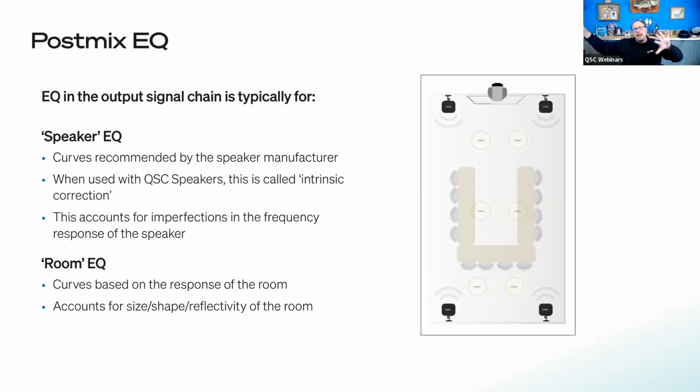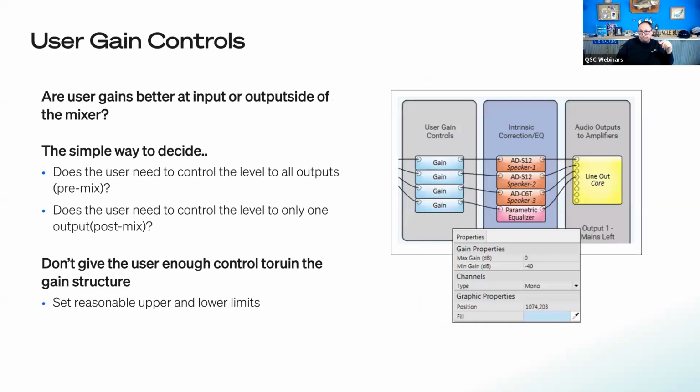But really, if every mic is going to be challenged by the same dip at, let's just say, 200 hertz and 700 hertz, like we had in our example, instead of having those little notches and 6 different parametrics on the front end, I could just notch out 3 or 6 dB on the outboard side for the mics. Now, if that becomes too large, you may want to keep it at the mics because you don't want the program audio to be missing those notches. It's just going to depend, but that's what you could see.